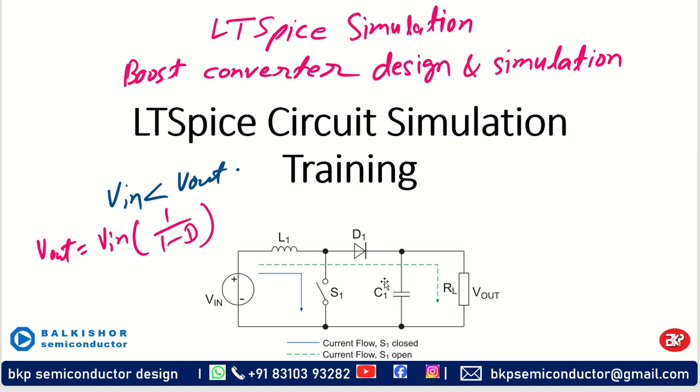Let us design and simulate a boost converter. You already know the configuration of a boost converter: we have an input voltage supply and one inductor which is going to charge and store the energy. During the on time, switch S1 will be closed and the inductor will be charging. During the off time, this switch is closed and this switch is open, so the current will flow from this direction to this direction.